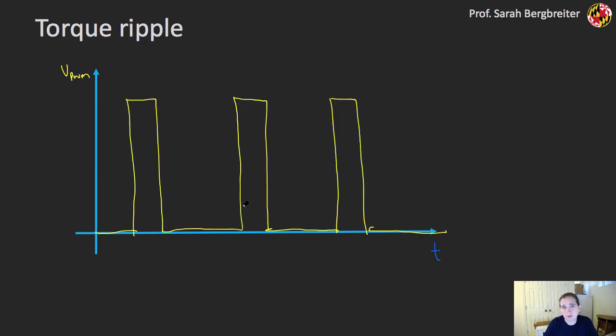So regardless of that PWM frequency, though, I am still going to get some ripple in the current that I'm applying to the motor. So when I make the motor voltage high, my current is going to increase a little bit, and when I turn it back down to 0, my current is going to decrease. And these are, remember, related to the time constants of the motor, specifically that inductance, tau is L over R. Typically that will be the dominant time constant. If you're operating at very low frequencies, the mechanical time constant might be dominant, but at higher frequencies, this L over R will be dominant.